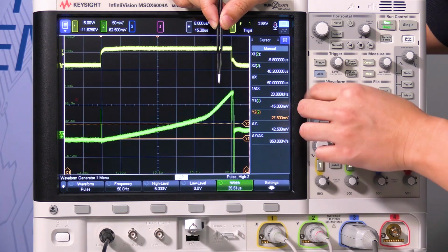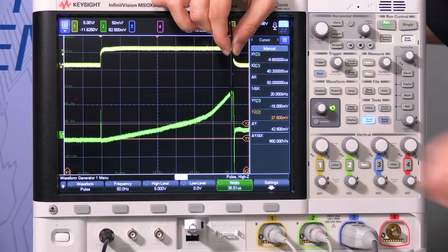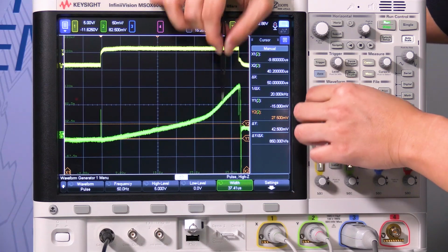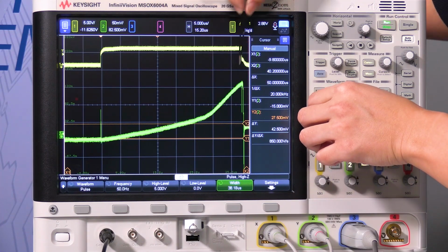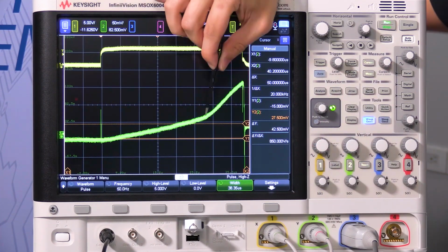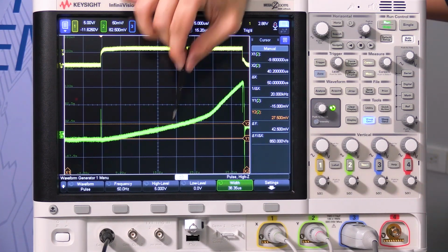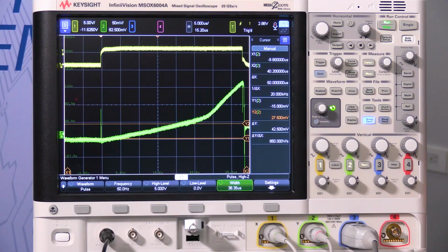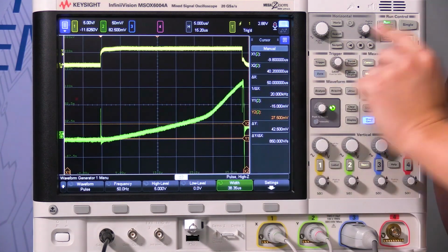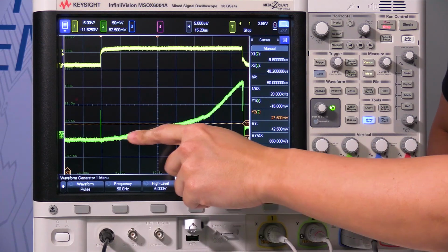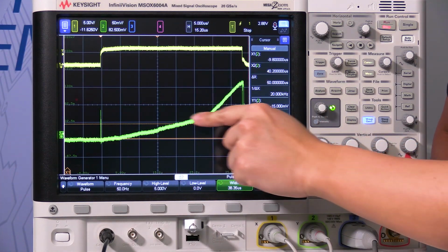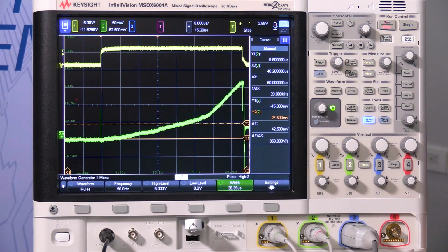Any voltage reported here, we can easily translate back into current using Ohm's law, which is V equals IR. So current will start to saturate once you reach this point in the knee where current starts to ramp up consistently high, because now you have saturated your core, and you no longer have an opposing magnetic field, so your current will just start to rise dramatically. So right here you can start to see that the current goes from linear to nonlinear, and that is the area where your saturation will occur.